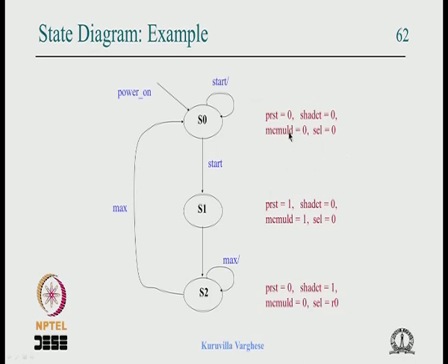Most of it is Moore output, but you see this select line is a Mealy output, because the select line is a function of some signal called R0, which is not shown here. It need not be the case that some of the input coming to the state machine needs to produce the Mealy output, it is not required. It can be something else, but which is related to the data path we are controlling. Naturally that has to happen. So the moment you have the state diagram, then we can write the next state logic and output logic, that is the most important thing.